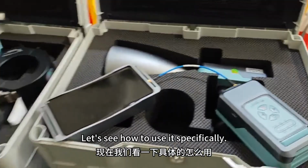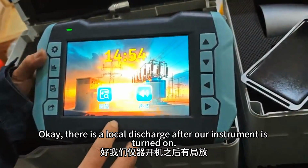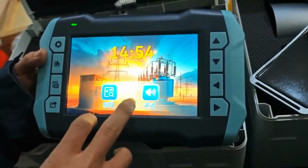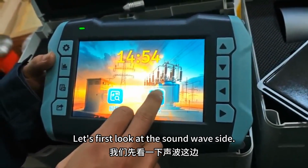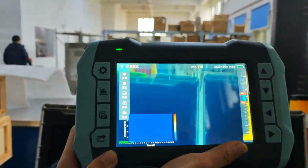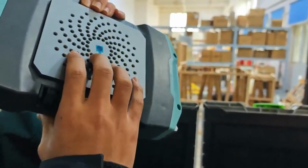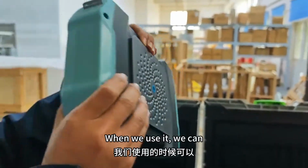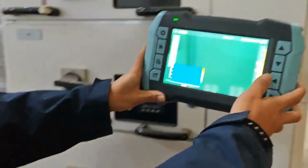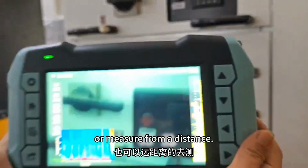Let's see how to use it specifically. First, we turn on the instrument. Okay, there's a partial discharge and sound waves after our instrument is turned on. Let's first look at the sound wave side. For the sound wave, we mainly use the ultrasonic probe on the back of our instrument and the camera. When we use it, we can stick it to the distribution box. It can be placed close to the distribution box or measure from a distance.